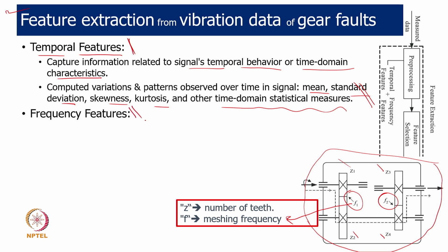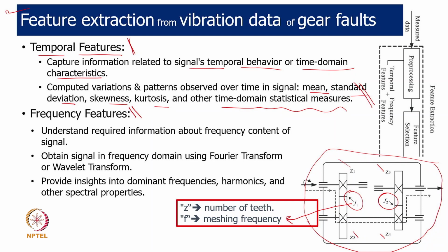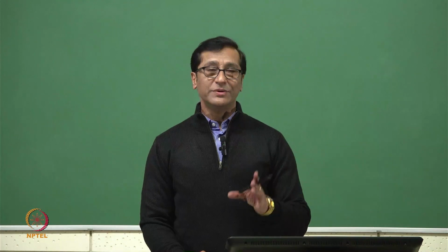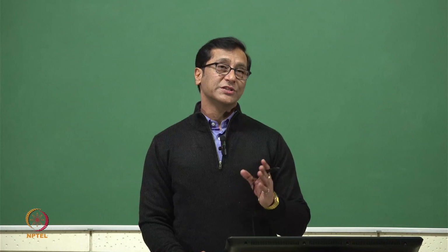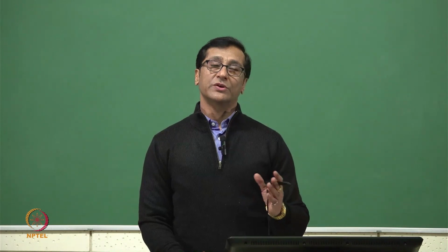However, I am giving a little more focus to the frequency feature because that provides more information to us. Understanding the required information about the frequency content of the signal comes from the literature. We know what kind of frequency response we are going to get from a gear, what kind of frequency response we are going to get from a ball bearing, what kind from seals, and what kind from a sliding bearing.